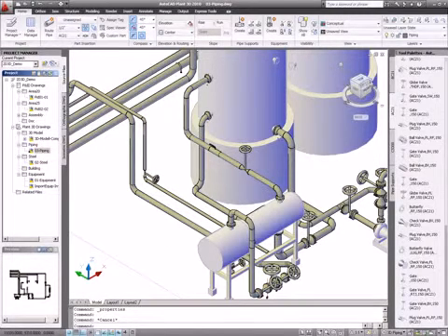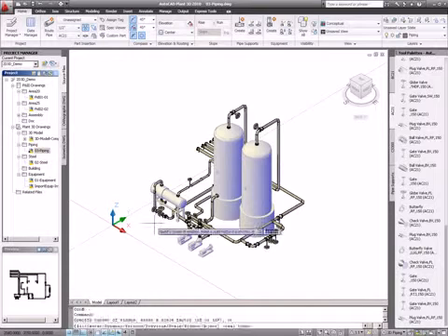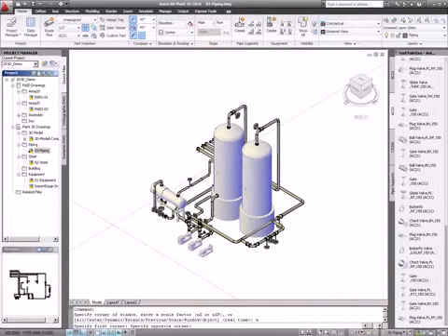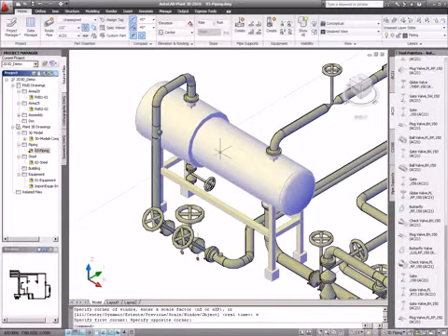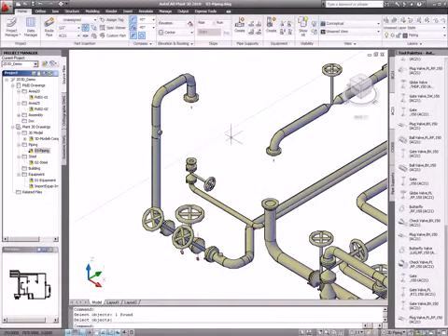Remember we talked about the bypass. Well, easily again, I use the cube to change to a different view. It's very easy to do. I do that. And again, let's see this tank. Well, I want to have only the pipe. So again, it's a very easy to use tool, hide selected, select equipment, and there you go. What I want to do is add a pipe between these two tees, reducing tee. And I also want to select it from a P&ID list.